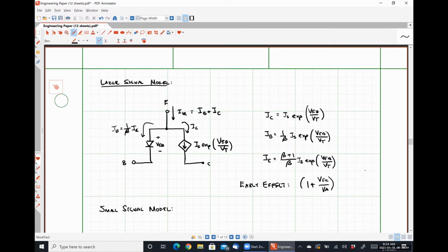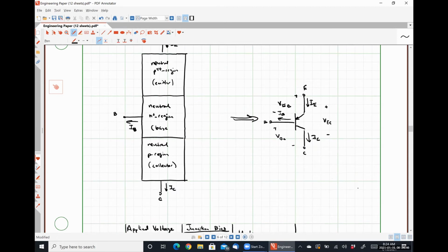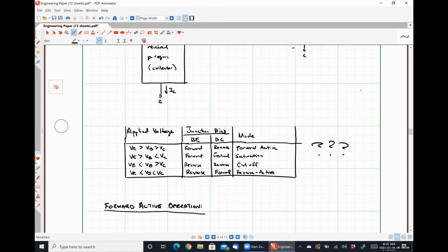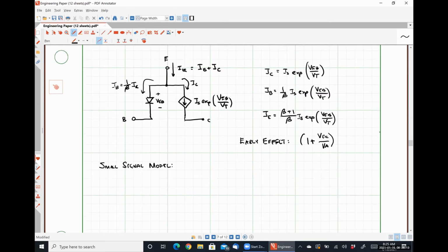Another thing that I may not have mentioned, so I'll go back and do this real quick. If we notice on the drawing here, the emitter is at the top. The arrow is still attached to the emitter, but now it's pointing in. For an NPN transistor, it was pointing out. The change in the direction of that arrow tells us whether we're dealing with an NPN transistor if it's pointed out, or a PNP transistor if it's pointed in. Sorry, I should have mentioned that previously. All right.